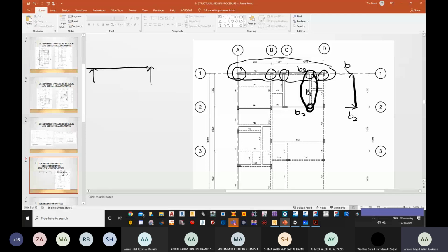So whatever we have learned, that beams can be supported by columns, beams can be supported by beams as well. Once again, in this scenario, beam number 1 is supported from one side by beam number 2, and on the other side by beam number 3. Are we okay? So now you can see that this turns out to be a simply supported beam or a partially fixed beam.